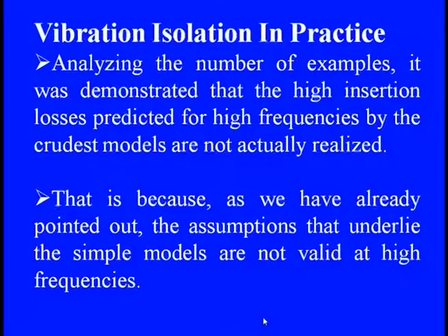When we talk about vibration isolators, we need to see whether the system is exciting at the lower frequency, at the higher frequency, or what exactly the forcing frequency is, along with the natural frequency of the system.